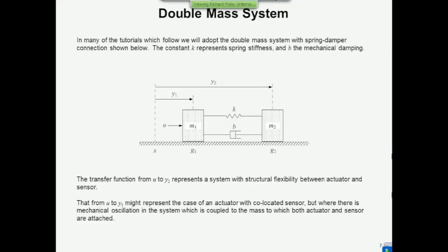Now, if I constructed a model of this, just like that, it's probably going to slide along forever because there's nothing to stop it. So what I've done is add a couple of frictional terms, because in reality there's going to be friction, and this kind of oscillation is going to die down for 2 reasons. One, because it is a little bit damped, and the other because there's sliding friction here that's going to bring these 2 masses eventually to a graceful halt if we just give it a kick.